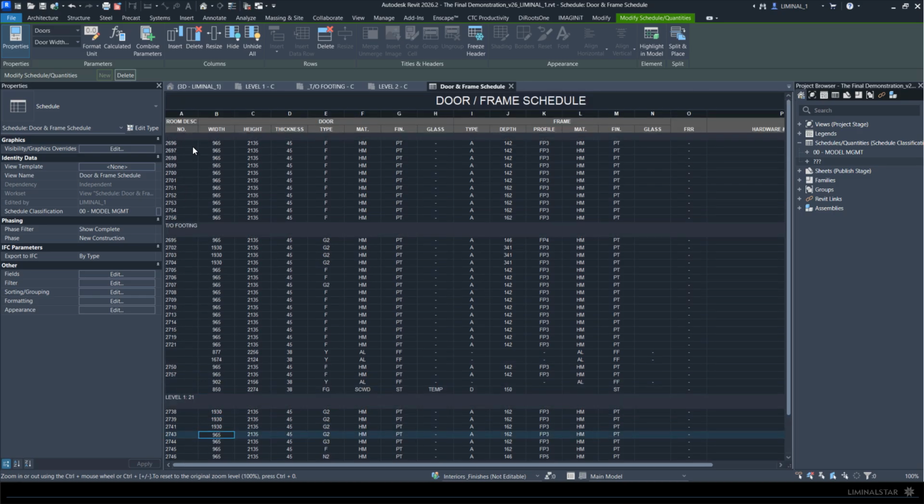And really, the way that this should be worked out is they shouldn't have a number of 2696, right? This is where you would get into a renumbering tool to change their instance parameter mark or their type parameter. So let's talk about that a little bit. We've solved our first mystery.